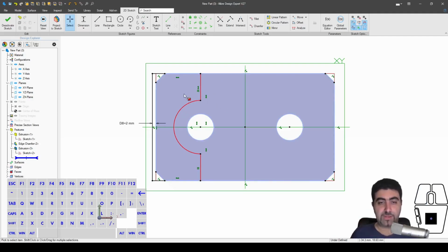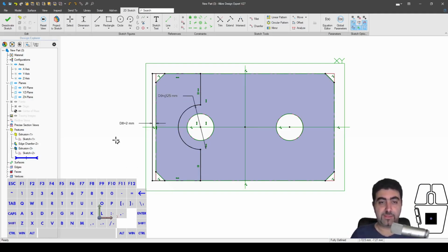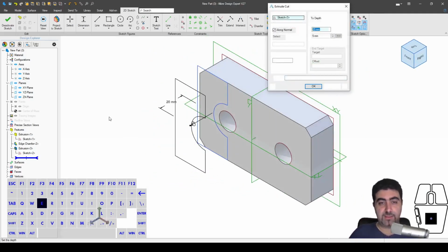Okay, but what if I wanted to give a diameter value here? So I click here. Okay, now wherever I move this, I'm only getting a radius dimension. But if I hold shift, then move my mouse ever so slightly, first of all, the text box becomes a little larger, and secondly, the leader now denotes a diameter. If I click, I get a diameter value. Okay, so now I can perform this cut and I have defined a diameter.